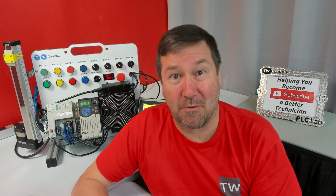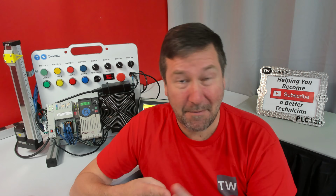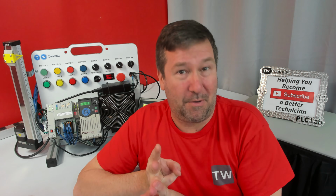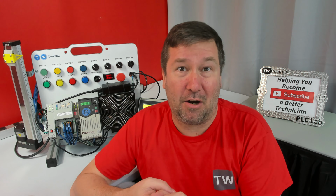Probably some of you are not running Ignition at work, but that doesn't mean that this isn't for you, because really all SCADAs have three basic parts. You've got to set up communications, you've got to set up tags, and then you're going to make the visual part. Now, yes, I know there are a lot more things to it, and we're going to learn a lot about those, but those are basically the same throughout all platforms.